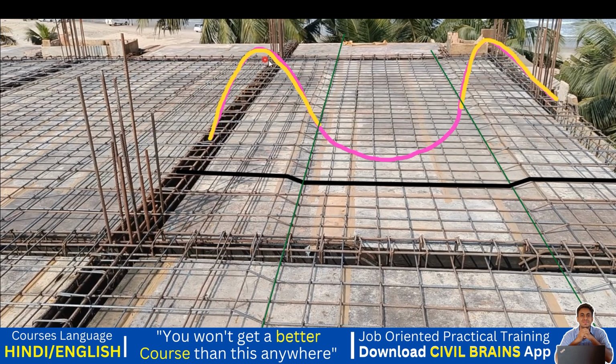My slab was trying to lift up, so I'm giving a crank bar here, that is, I'm giving a top reinforcement. In the bottom my slab was trying to come down, that is, it was a sagging bending moment. Since it was a sagging bending moment, I don't require a top steel, I have to provide a bottom steel. That is why you can see here we have provided the steel only in the bottom. Got it? So this is the main idea behind that.